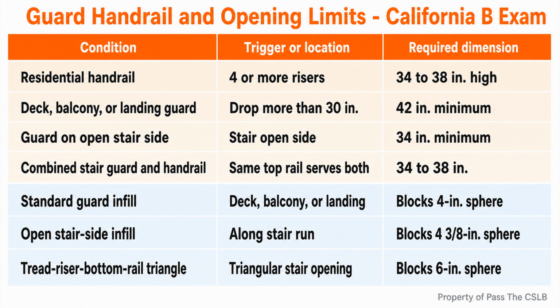That difference matters because a contractor can correctly remember the permanent tolerance and still apply it to the wrong stage of work. I use two mental folders. Finished permanent stairs go in the Title 24 folder. Temporary worker access goes in the Title 8 folder. The dimensions are related, but they are not interchangeable.